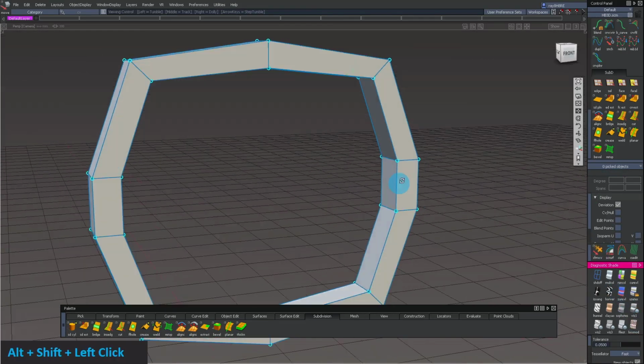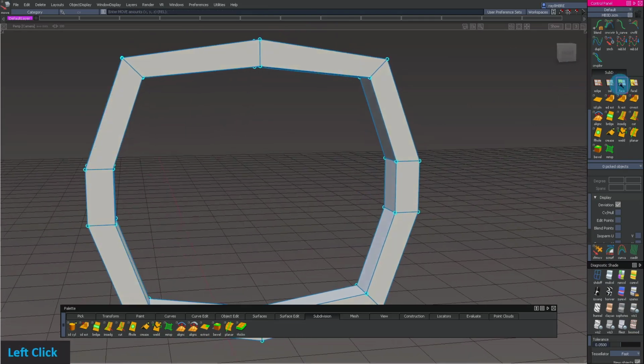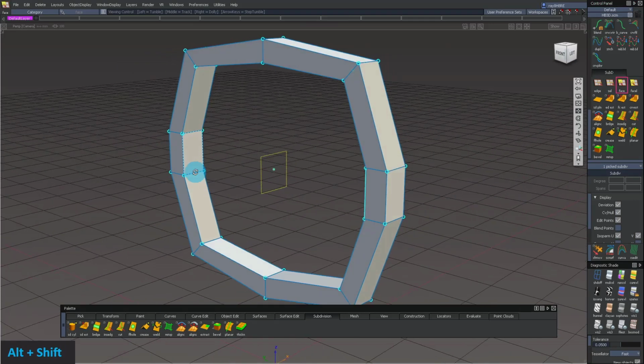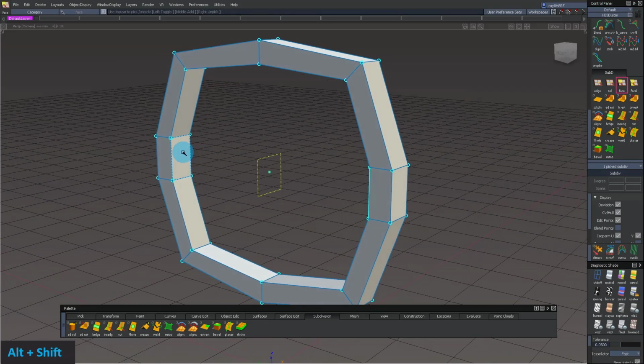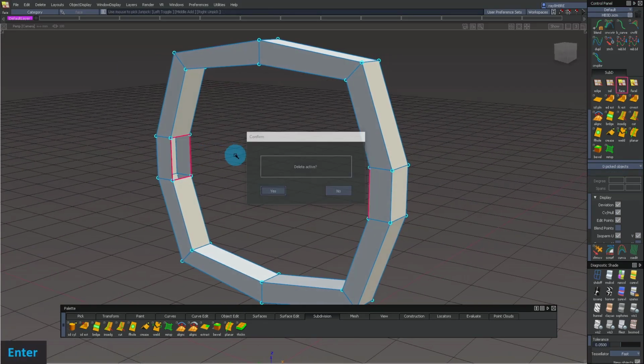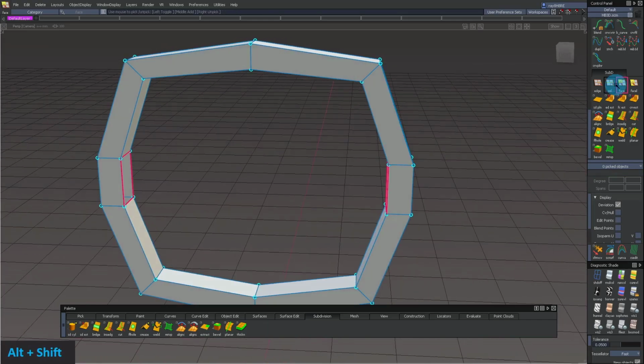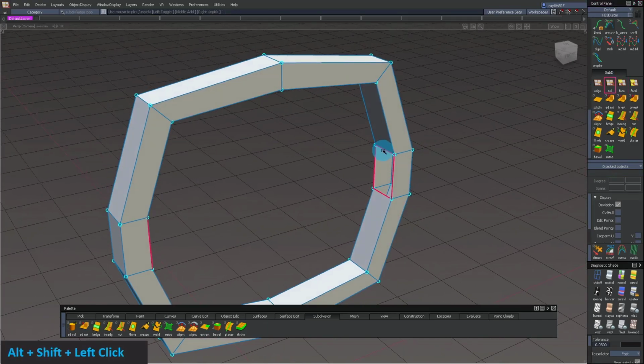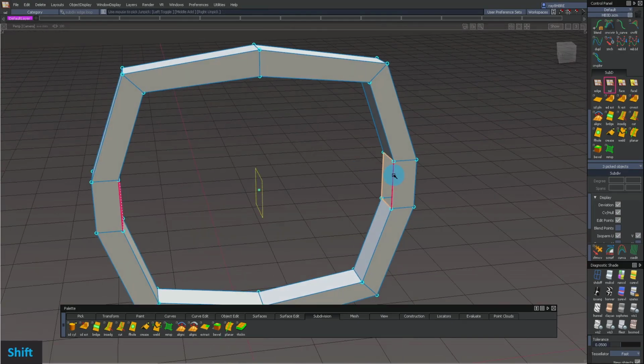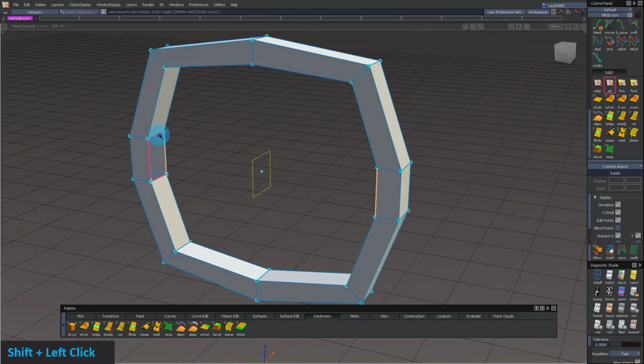And from there, I'm going to move it around and try to get a better turning radius of the edges. And now I'm going to go into box modeling, and I want to get rid of the face that's right there in between, right? So I'm just going to select that face and select the other side and then press delete. And actually, I don't think you need to select it when you're in mirrored mode. It just does it automatically. And now I'm going to select these openings, and then I'm going to use my bridge tool to make a surface between both of them.